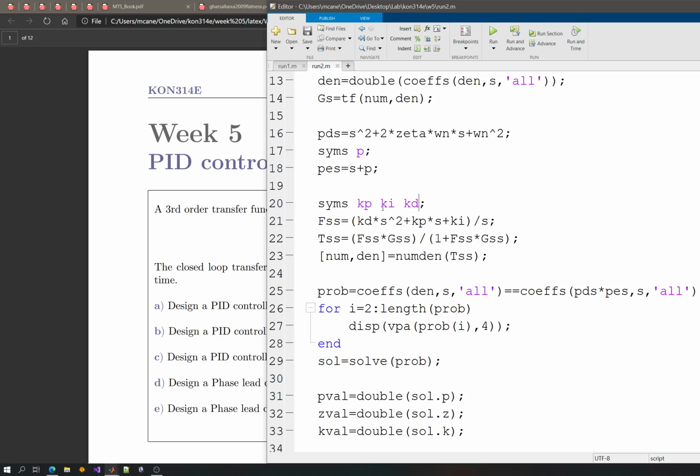Now, I have a third order system. I'm adding a pole. It will be a fourth order system. Now things will be changing since I have used a cancellation, a pole zero cancellation during the design in A. I did end up with a third order system since my controller was adding 1 degree but also canceling a pole of the system, so the degree didn't change.